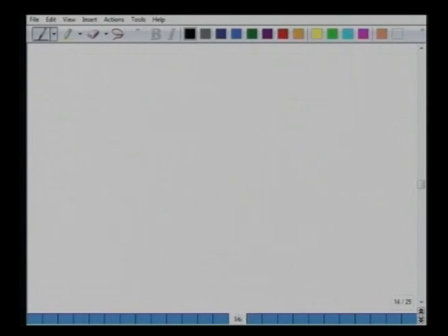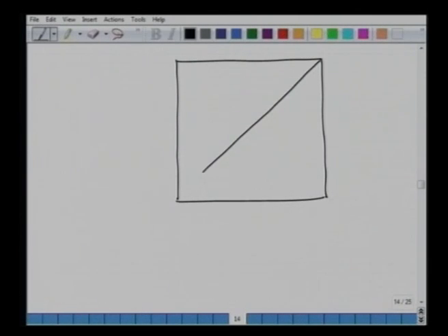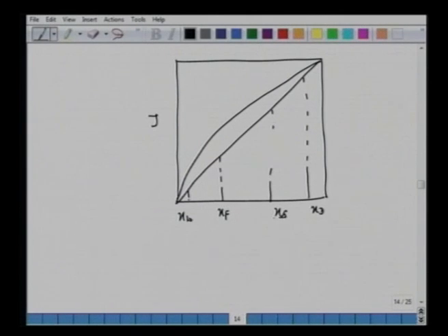So what happens to the McCabe-Thiele plot now? Now you have two side streams. Again you start from y versus x. All right, you have x_D the top product, you have feed x_F, you have the bottom product x_W, and now also you have x_S. So now you have four streams, two side streams now, x_S and x_D, and we have one feed entry and one withdrawal product x_W here. So what you will expect, the first operating line which we wrote will go from here to here. The second operating line for the bottom product which we wrote like this will go from here to here. So there is a feed here. Feed will give this feed line, Q line.